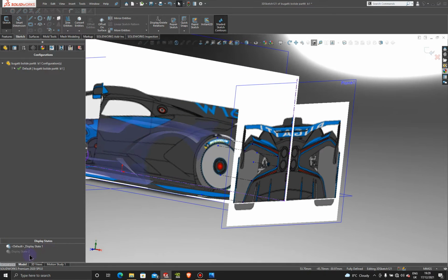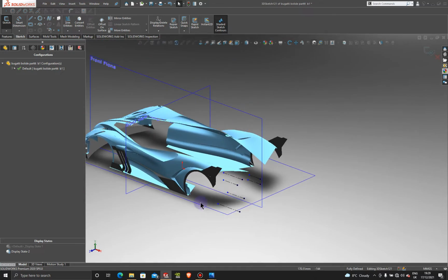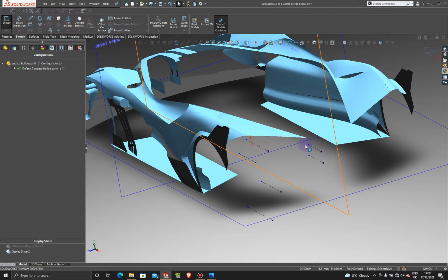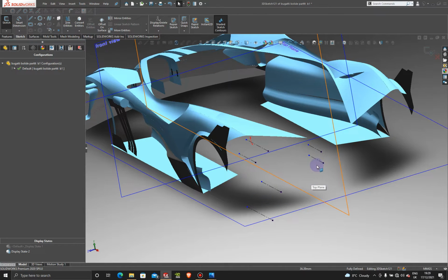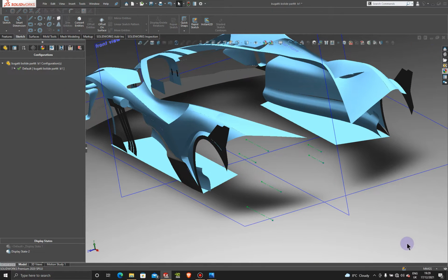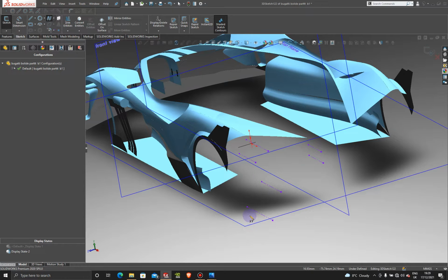All right. So now if we jump over to a second display set, right? All we have to do now is connect these points, and that will create this geometry on this side. So exit the sketch, and then let's jump to the 3D sketch, and we're going to use splines, and we're going to use these inner points, not the other ones.